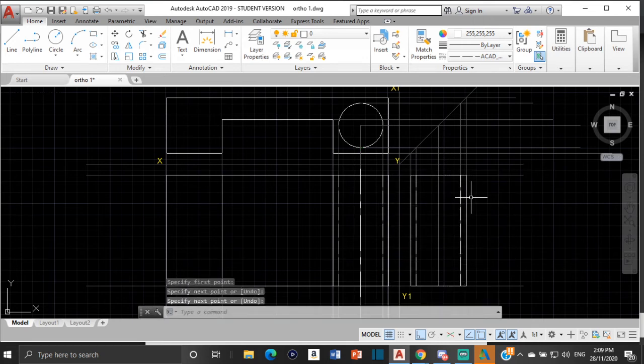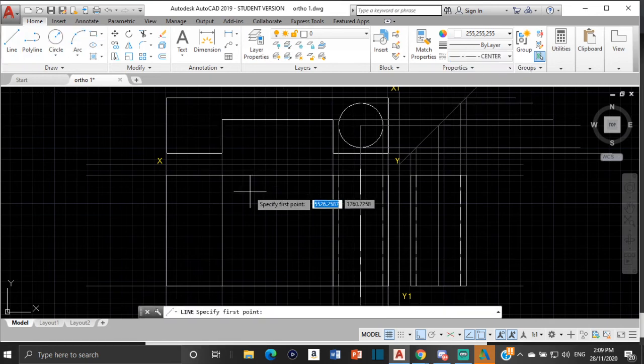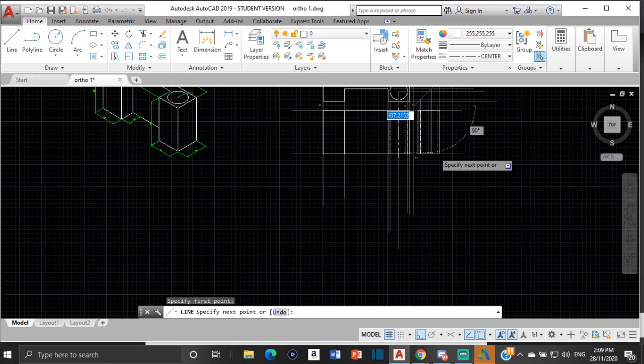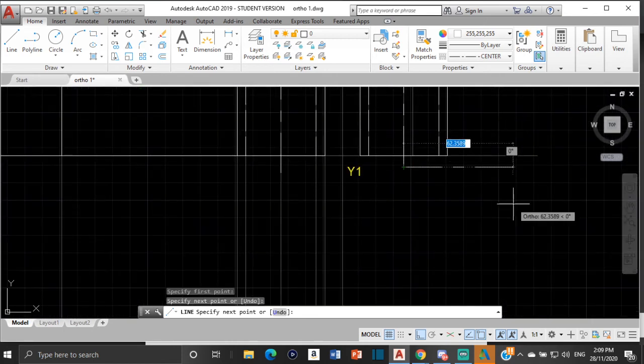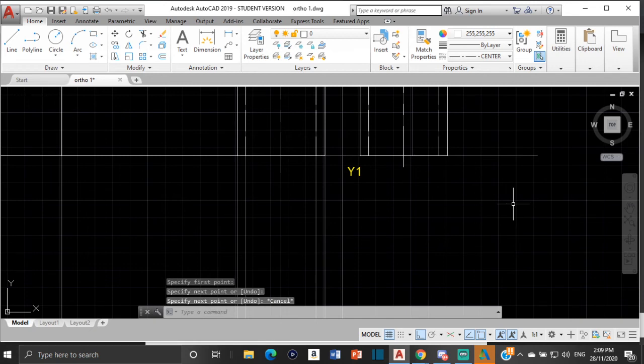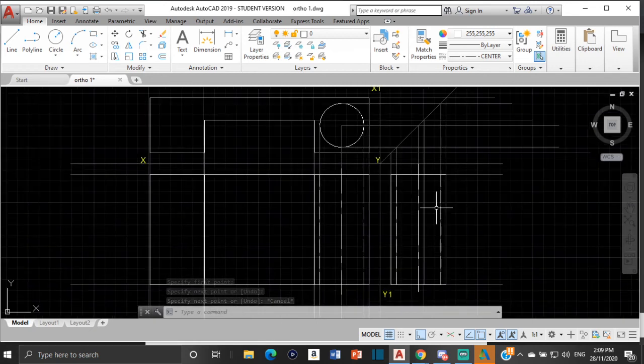Lovely. Then now, we have this line going across to meet the 45-degree line. Alright, we have a line from here going across to meet the 45-degree line, and then it goes down. So that's the line from the center of the circle. So because it's the line from the center of the circle, we use a center line. And then we're going to draw this down. But we're not going to draw it down exactly from here. It's a center line. So you start it a little bit outside of the drawing. Like that. And then bring it down. And bring it a little bit outside like that. Right? That says it's a center line. Now I know that that's a circle. Well, that's a circle, a hole.